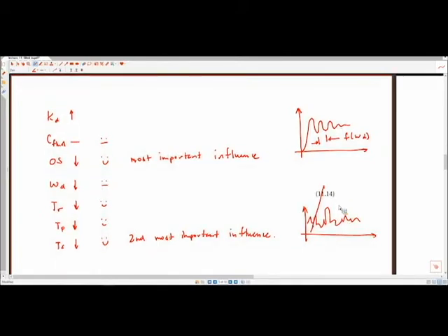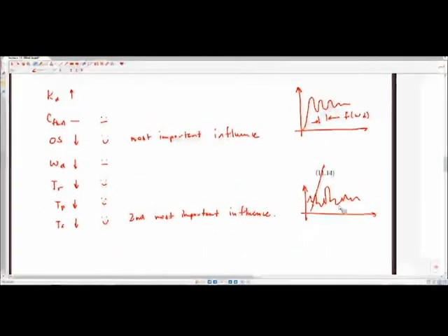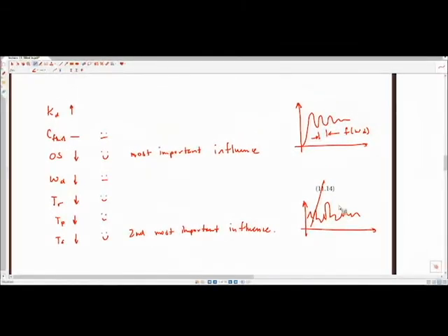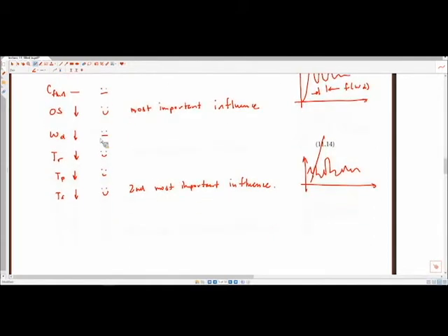All right, so you may look at this, right? You look at all these mappings, you say, okay, we've handled some of the rise time issues, we've handled the settling time issue, we've handled the overshoot issue. The one thing that we really haven't satisfied yet is how do we get C final to be equal to our actual value we want, right? And so, lo and behold, we have an answer.